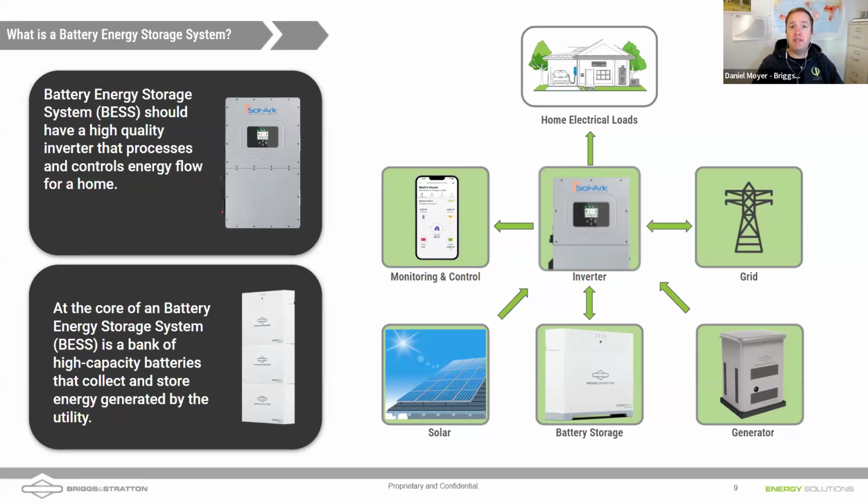Yeah, in addition to having the inverter, which can take the DC, turn it into AC, the Solar has a battery charger, right, that can take AC that's coming out of the grid, AC that's coming out of a generator, turn that into DC and charge up the battery as well. And Nathan, a lot of times this has been historically what we've done in off-grid systems. You would just get rid of that little grid icon, and if the grid goes down, that's essentially what you are. You're an off-grid home.